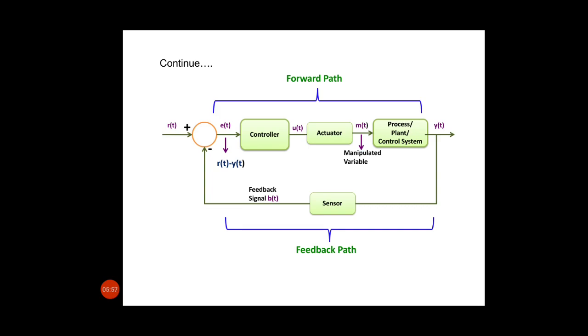Now the question we need to ask ourselves, if we design a closed loop control system, is what is the time scale of the sensor response with regards to the time scale of the system response. For example, if the system response is at a second, and I have a sensor which can provide accurate measurement in a matter of milliseconds, then I may not need to worry about the sensor dynamics.